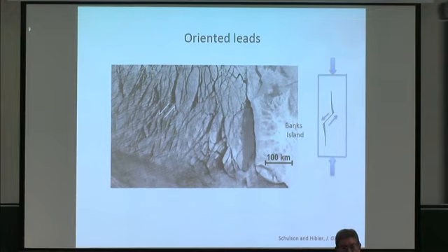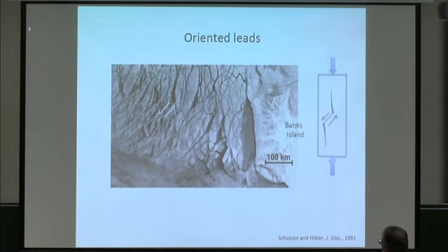And we would interpret that process within the classical, going back even to Griffith, 1920, sliding crack phenomenon, sliding along a parent inclined crack, generating tensile stresses at the tip, which are relieved through the development of extensile cracks running along a direction of loading compression. So the hypothesis Bill Hibler and I produced at that time was that this is a frictional sliding type process, and that what we're seeing here is evidence of a failure under a compressive state of stress.